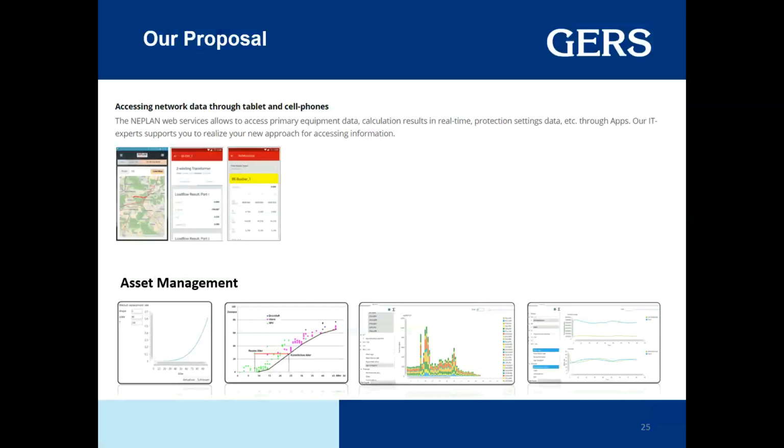So the purpose: why do you need to integrate the asset management system with the simulation of the network? The first topic that I think here is, for example, the reliability. Because, of course, if you would like to increase the power quality, the quality of the service, you will have some indicators like the reliability. And those criteria are coming from the simulation of reliabilities. I mean, you need to automate a lot of load flow solutions, a lot of combinations of load flows, because with the load flow you will be able to identify how much energy you are not supplying if you have a fault.